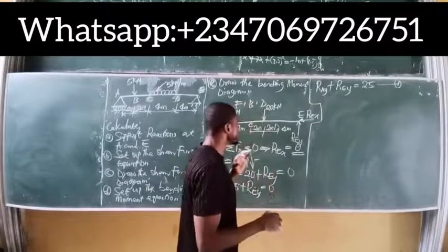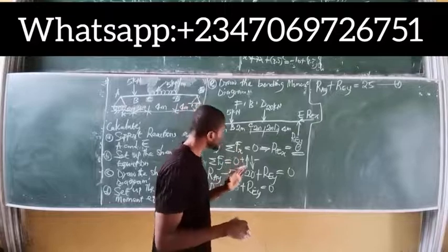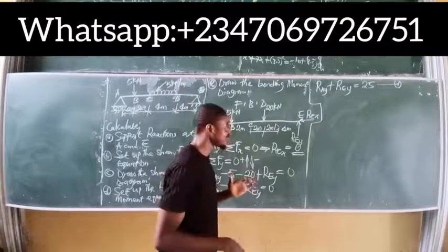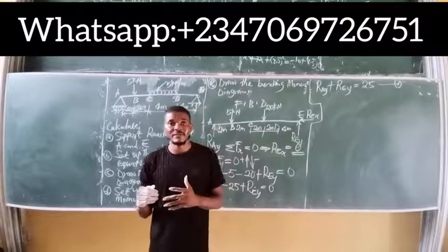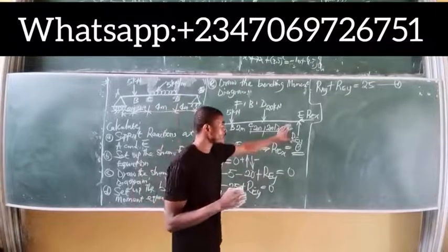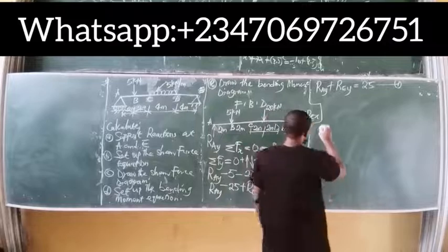Take moment. And which place is best to take moment on this beam? About point E. Take moment about the point where we have numerous forces. Okay, so E is better for us to take moment. Taking moment at point E.